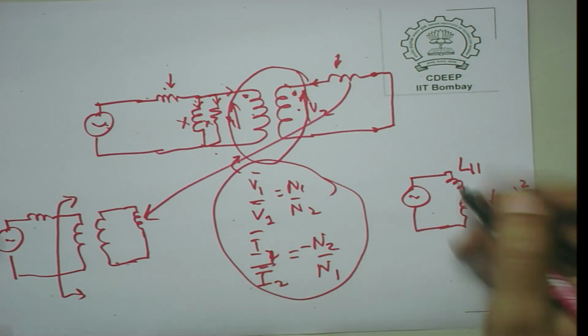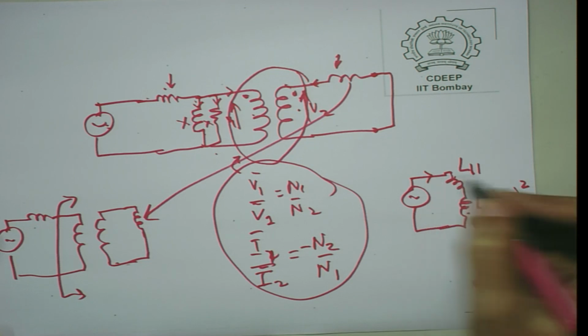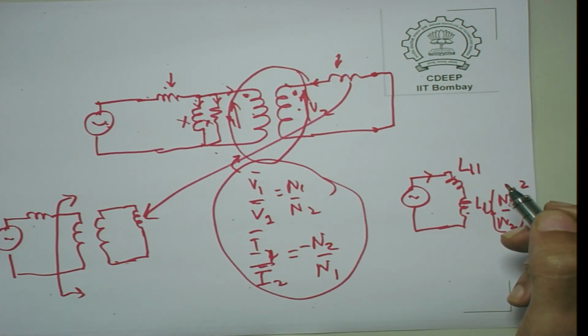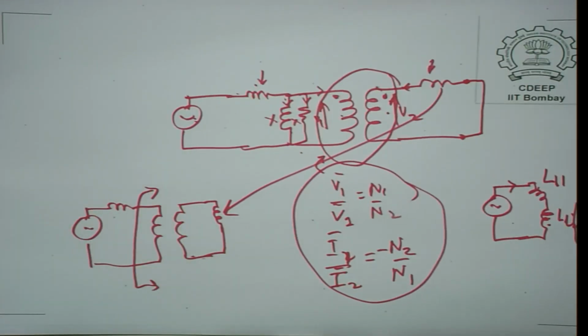If the leakage is more, the current flow is going to be less when you carry out this short circuit test. The test is carried out on two identical transformers. The only difference is that one has more leakage and the other has less leakage. The taller one has less leakage, the shorter one has more leakage, and we will test this conjecture by actually doing this experiment.